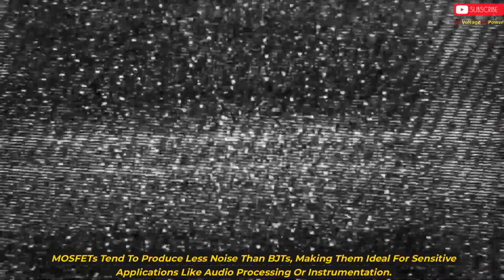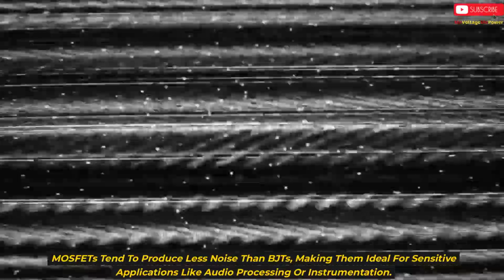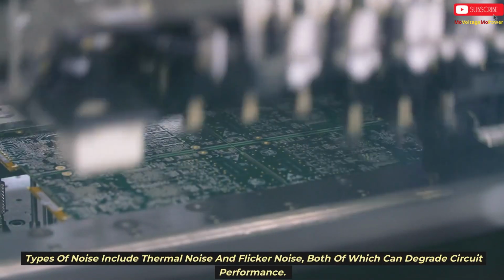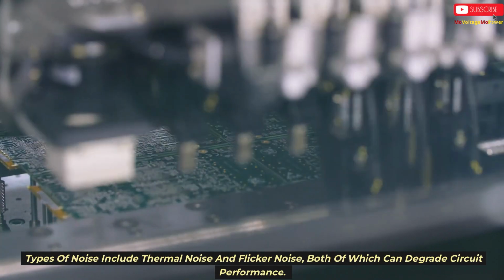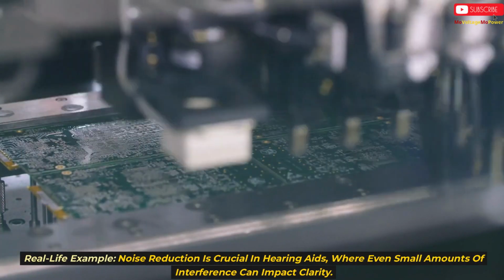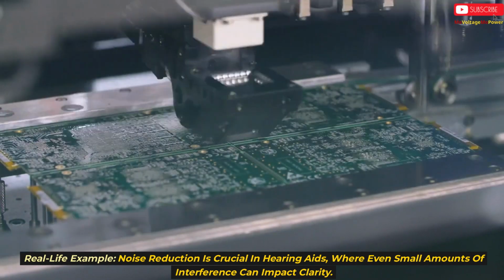Noise and amplifiers. MOSFETs tend to produce less noise than BJTs, making them ideal for sensitive applications like audio processing or instrumentation. Types of noise include thermal noise and flicker noise, both of which can degrade circuit performance. Real-life example. Noise reduction is crucial in hearing aids, where even small amounts of interference can impact clarity.